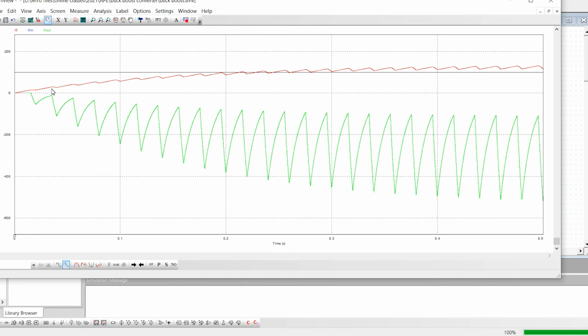There won't be any discharge from the inductor, but there will be discharge from the capacitor, like I told you earlier. That is why the value of the voltage will be reduced, but not to 0, and still there will be voltage across the load. This is the part where the discharging of the capacitor took place, and from here the next cycle repeats.